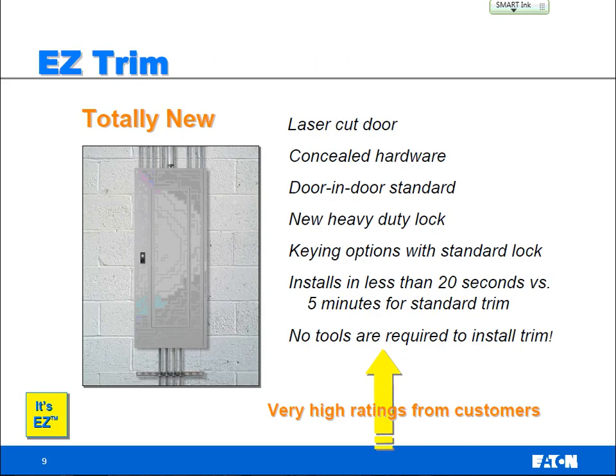It's safer too. Much safer, yep. If you're working energized, you swing it open and work, versus trying to align the trim and accidentally having the corner get into one of these phases, and you shorted it. So yeah, if you're doing it hot, especially. If you're working on an energized panel, you need to minimize any chance of danger.